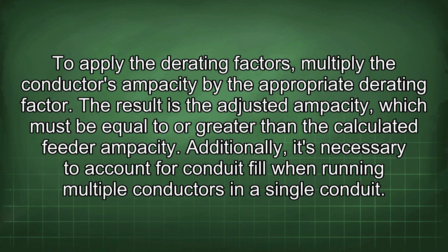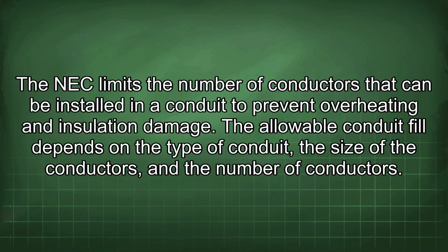Additionally, it's necessary to account for conduit fill when running multiple conductors in a single conduit. The NEC limits the number of conductors that can be installed in a conduit to prevent overheating and insulation damage. The allowable conduit fill depends on the type of conduit, the size of the conductors, and the number of conductors.